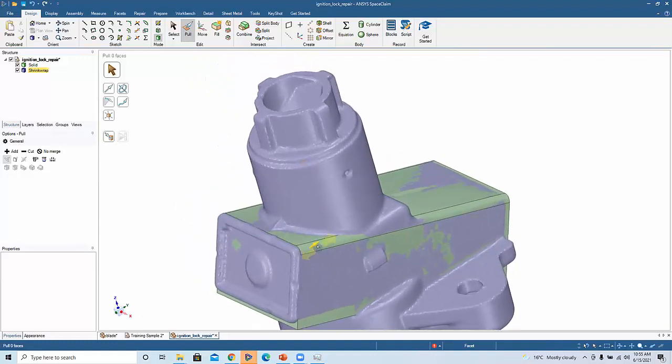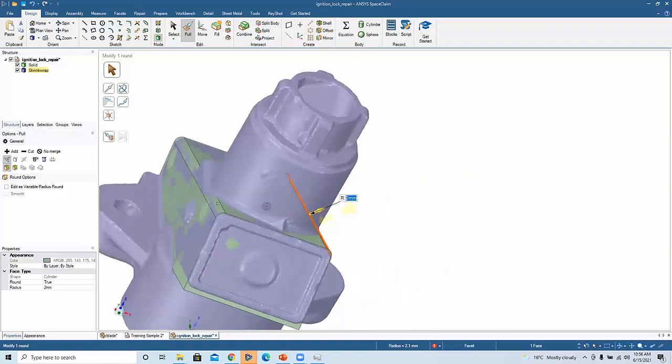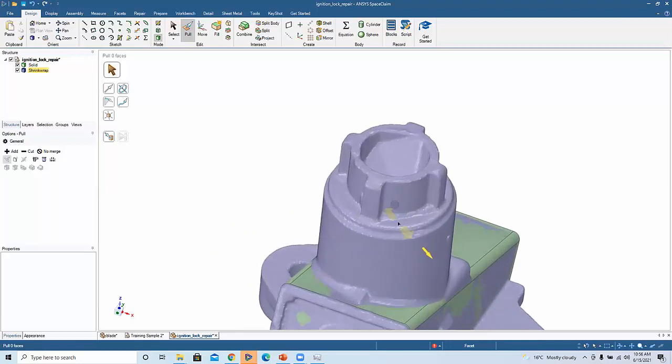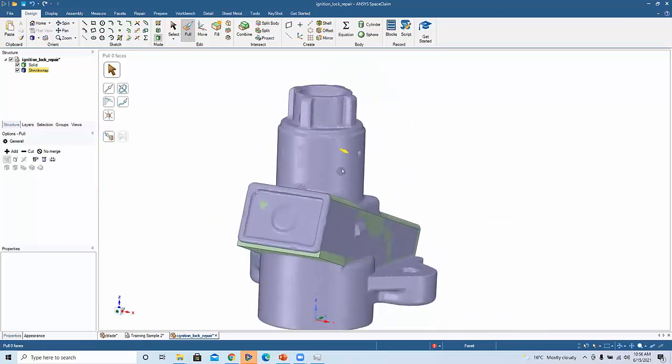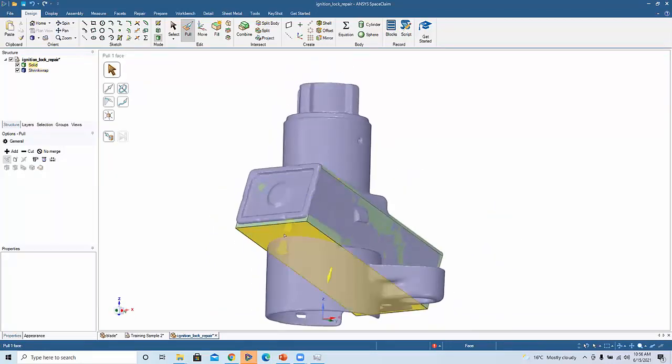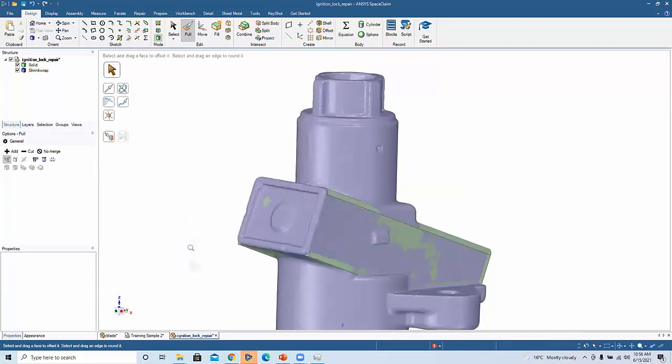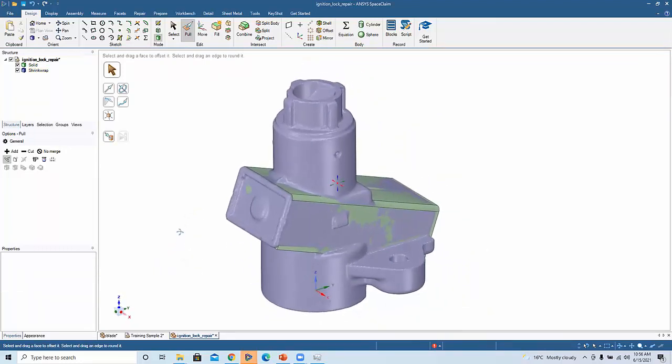Now, sometimes when you're trying to get the intent, you'll notice here this says 2.1 millimeters. Maybe this is close to an imperial model, or maybe this is actually meant to be in millimeters. So maybe it's supposed to be 2 millimeters, so I'm going to readjust. But at the very least, it'll get me close enough to the size that it was intended for when the design was done. That's a very important thing when you're doing reverse engineering: being able to grab the features and snap up to the mesh dimensions, so you're getting an accurate view of what the actual model is supposed to be.